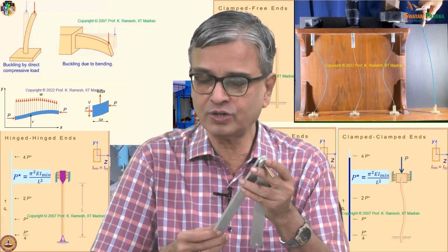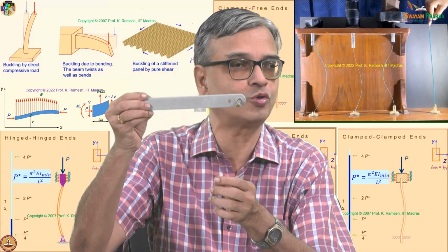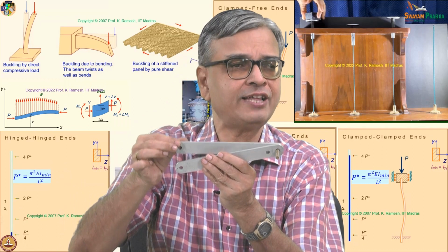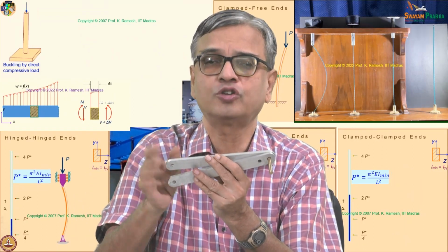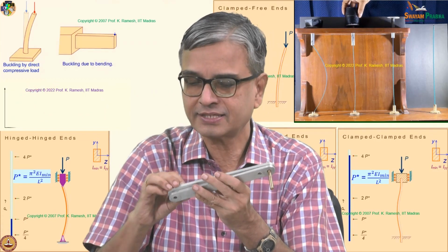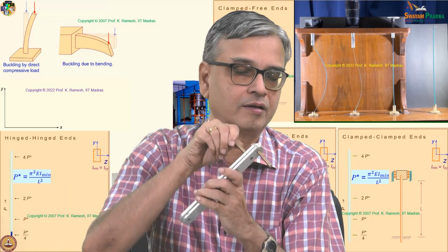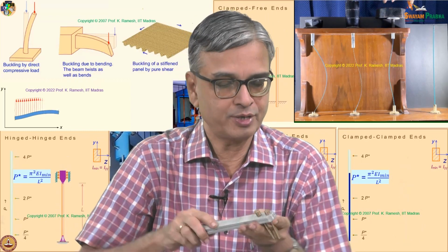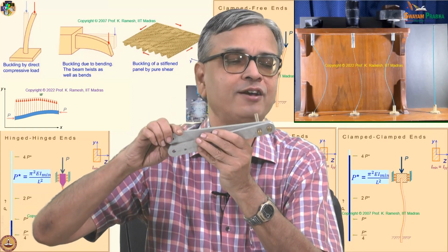So, now what I will do is, I have two holes, okay, I suppose you are able to see two holes. I have put one pin and I am able to freely rotate. What do you say as fixed end? It should not rotate. Fine. Suppose I put another pin, probably you can see this better. I have two pins and I am trying to rotate.